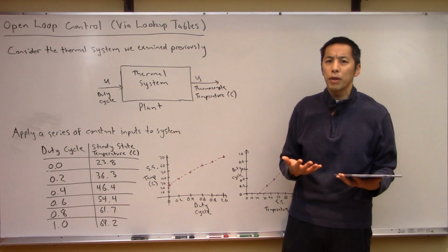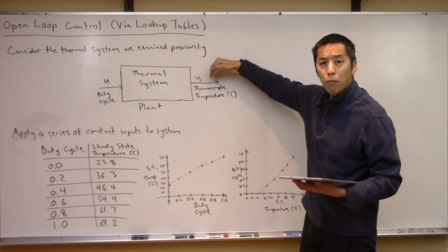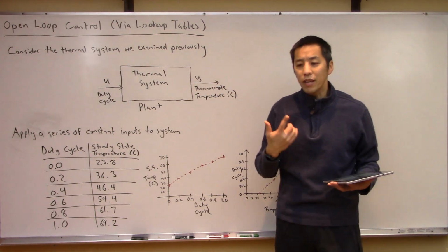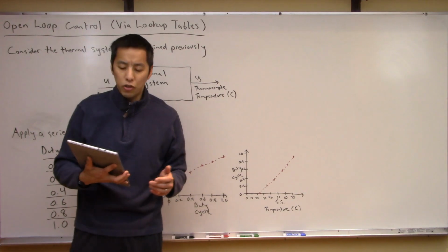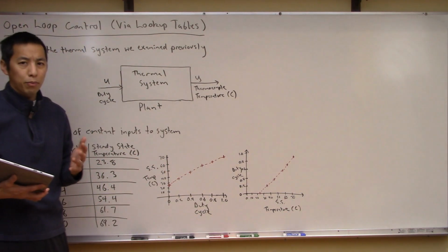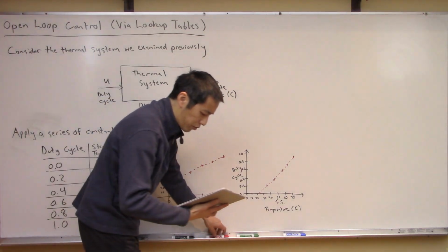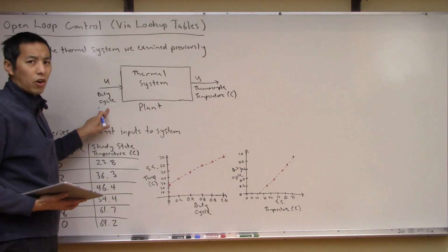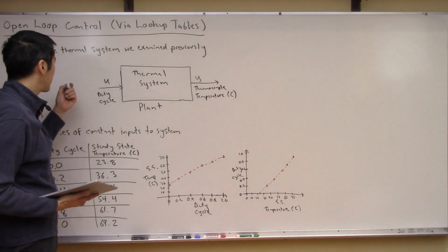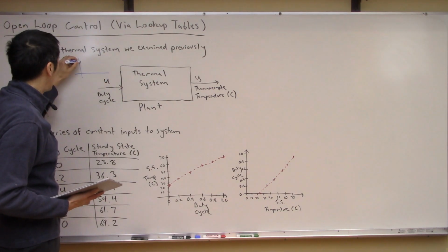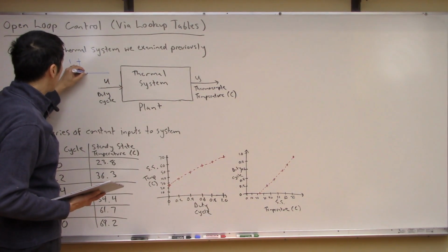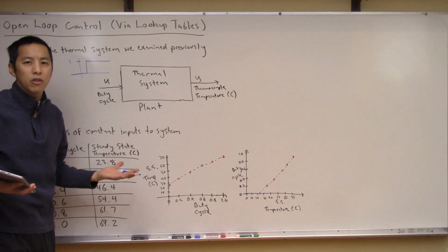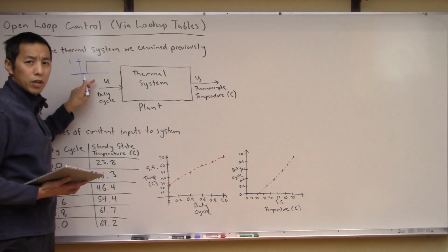And now what we want to do is we want to be able to control this system and say, how can I get the output to be some signal or some value that I care about, okay? So the easiest way to go about this is to do sort of a dumb brute force approach to this. What I mean by that is, let's do something really simple, like, for example, on the input duty cycle, let's just start with some very simple test signals. For example, why don't I put in a duty cycle of 1? So I'm just going to start at 0, 0, 0, and then at some time I'm just going to step the input up to 1 and hold it steady, okay? That's about the dumbest thing you can do with your system, right? It's just set the input control signal to some constant.